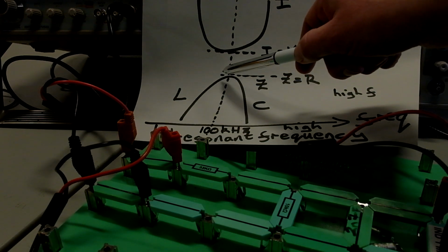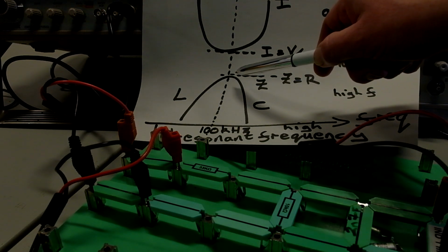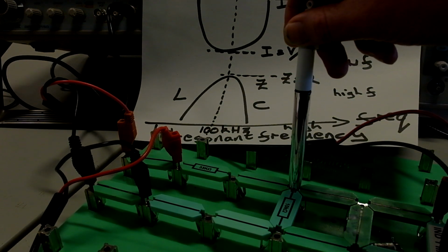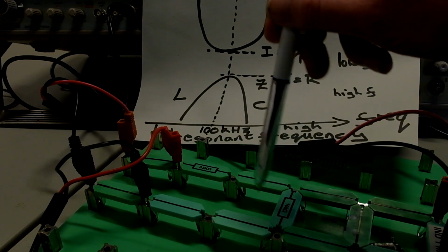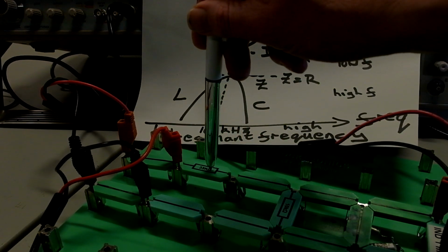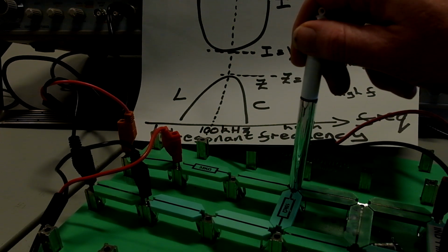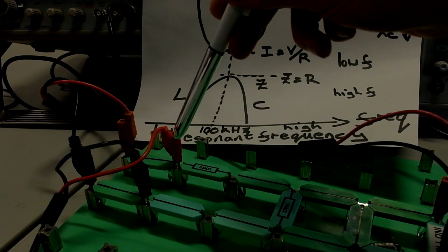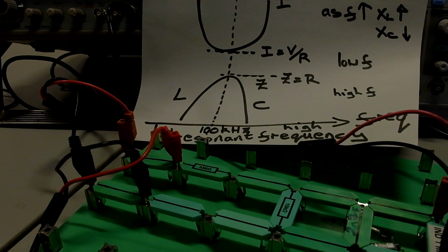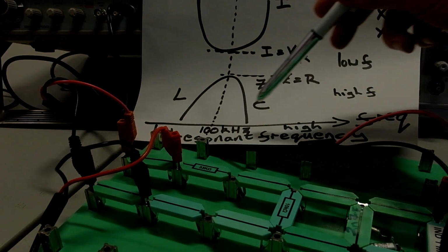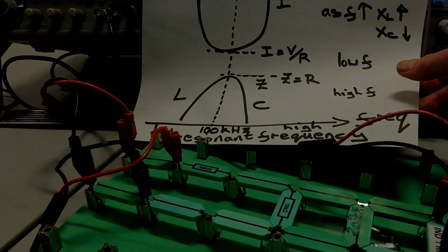So at peak input impedance, or impedance of the circuit, we get maximum voltage coming out at this point across the parallel network. So why have we got a voltage divider here? This resistor is put in there to create a voltage divider so that we can actually see a separate output voltage, discriminated from the input voltage here, and we can see on the screen that the voltage reaches a peak at a particular frequency of 97 kilohertz, or round it off to be 100 kilohertz,